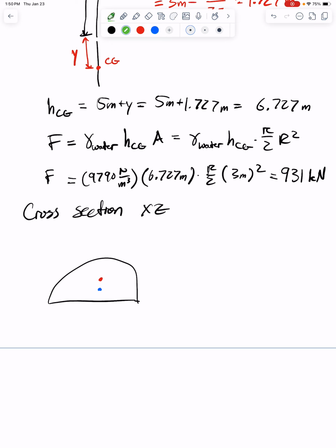I need to figure out YCP. So, before we start, the second moment of inertia for a semicircle is (9π² − 64) divided by 72π times r to the power 4. So if this ever shows up, hopefully it's on the equation sheet or in the problem.